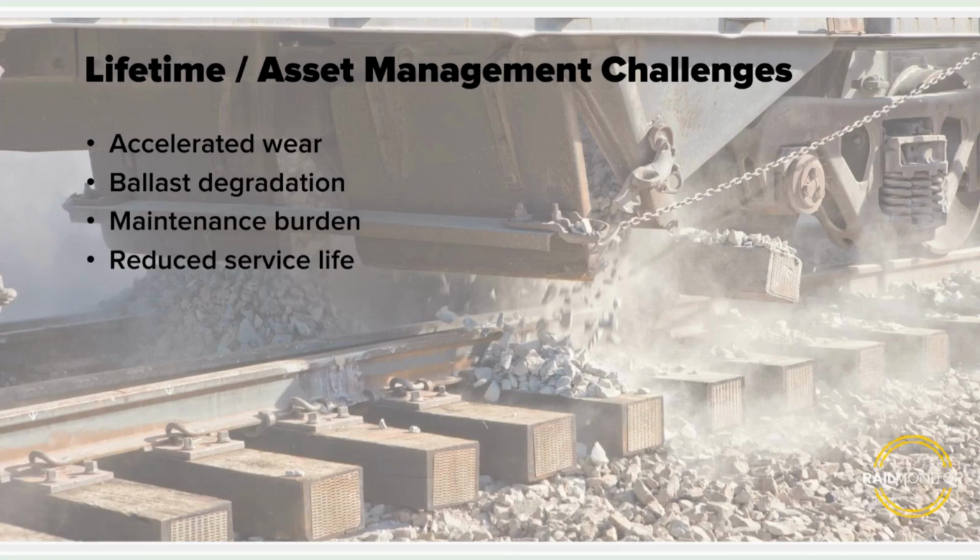For the lifetime and the asset management life, there will also be accelerated wear. These repeated impacts accelerate the rail corrugations, maybe also sleeper cracking, and the ballast will also be crushed and then not have these elastic absorptions anymore and be more stiff.